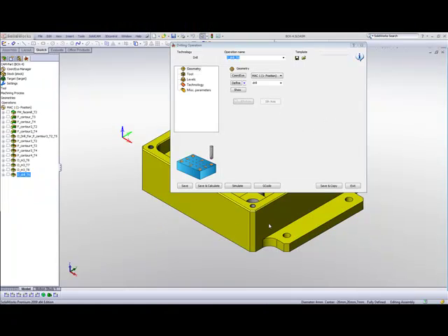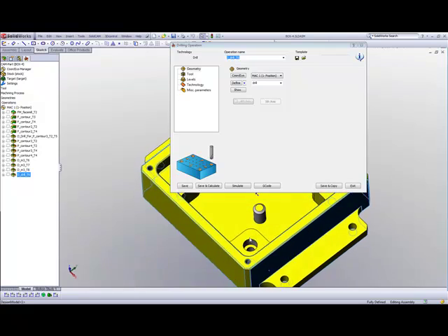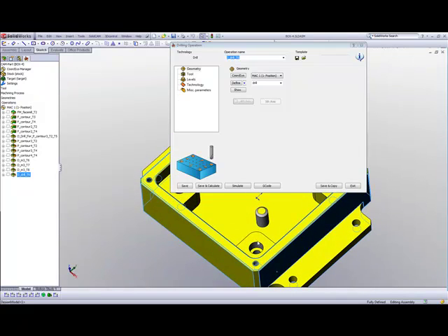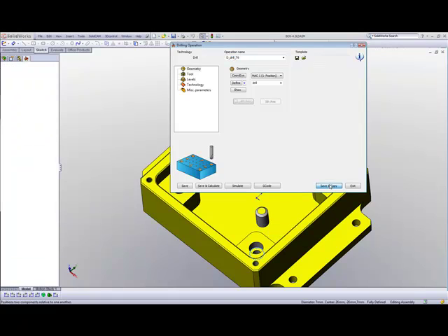Now in my next operation, I'd like to actually go down with the 7mm drill that I need for here, to go down to this surface as you see over here, but I want to have the tip of the drill go a little further down, causing a chamfer on this hole over there, which does not exist yet. So I'll simply do save and copy.